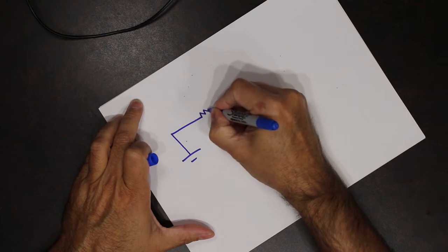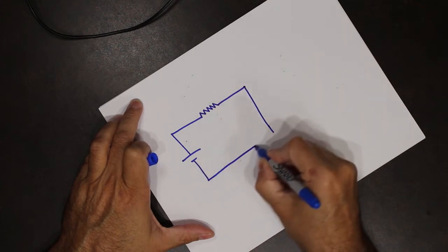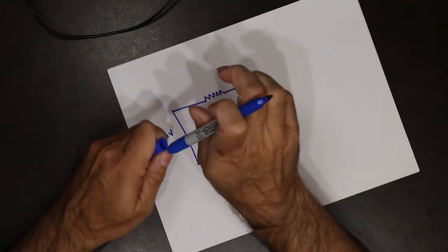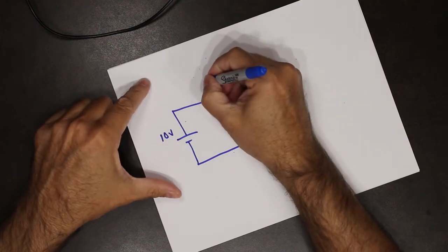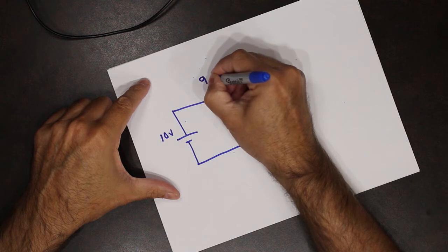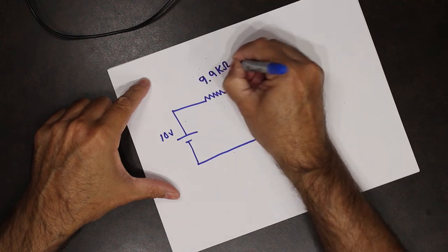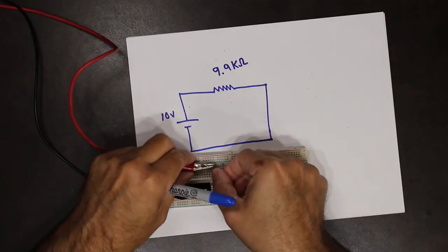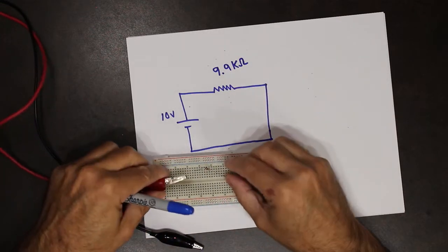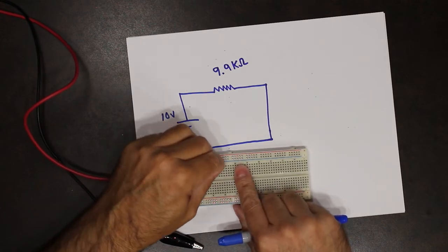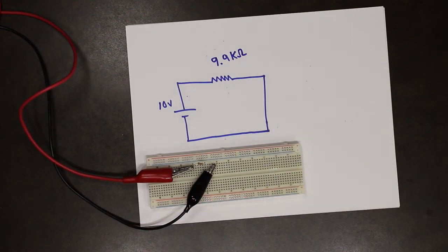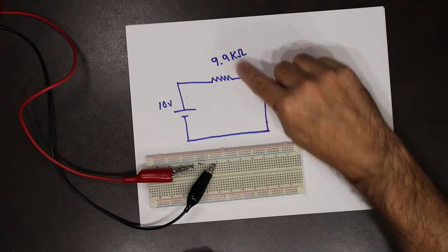So let's take a basic circuit. One resistor, and I'm going to apply 10 volts. That resistor is the one that we are utilizing, and it was 9.9 kilo ohms. So here is that circuit right there. Okay, so this resistor was the 9.9 kilo ohms, supposed to be 10, remember? And then I've got my 10 volts attached. So there's 10 volts across that resistor.